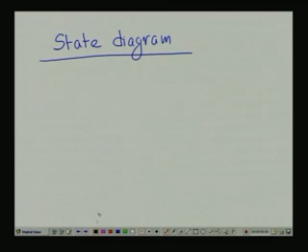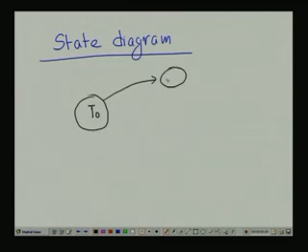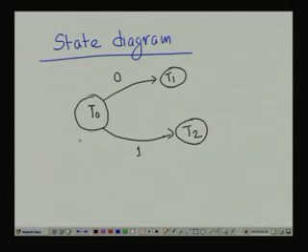The state diagram will be like the initial state T0 coded with 0 0, then it will go to 0 1, means T1, if it is a false path, and if it is a true path then it will be T2, that means it is 0 0, 0 1, 1 0. So, this is the state diagram of the ASM.